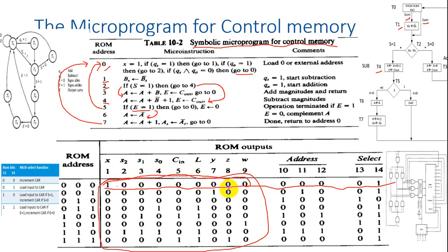One part is called the branch address. This is the branch address. That means, in case you need to branch to some other location inside the program, this would be the address used to go over there. And whether the condition is true or false, that means if the condition is true, only then you load the branch address. Otherwise, you will not load the branch address. You will load the next line.